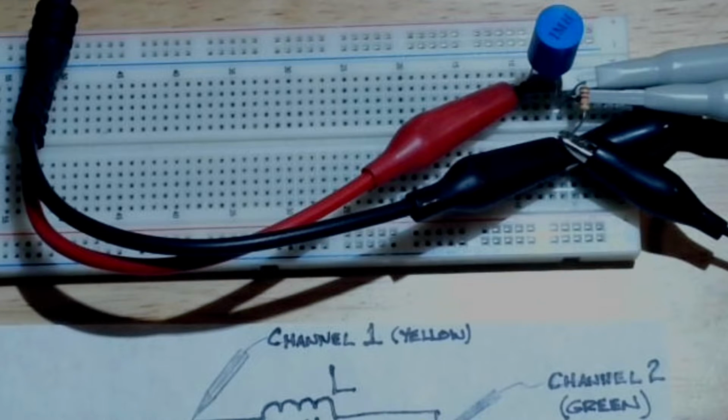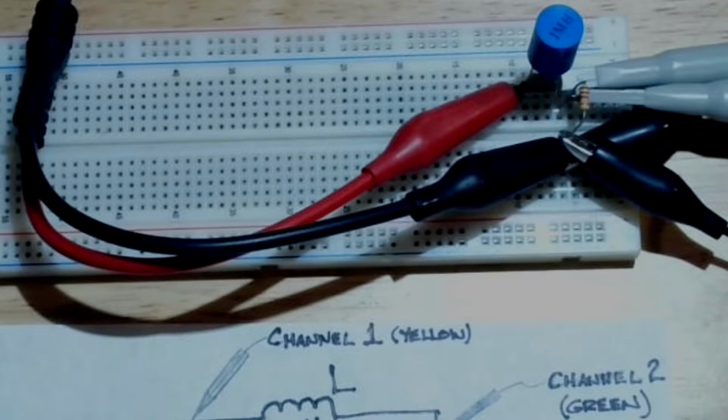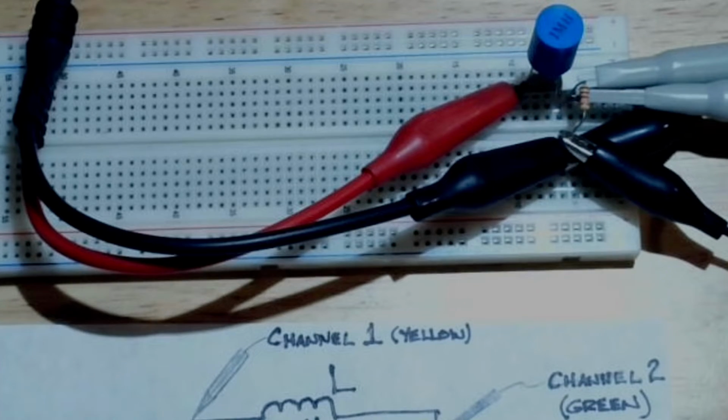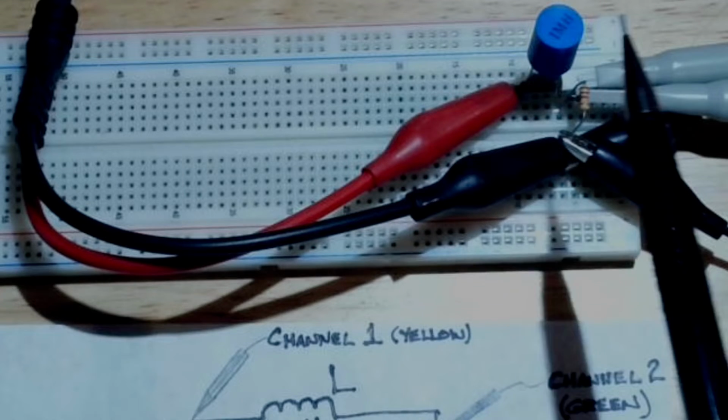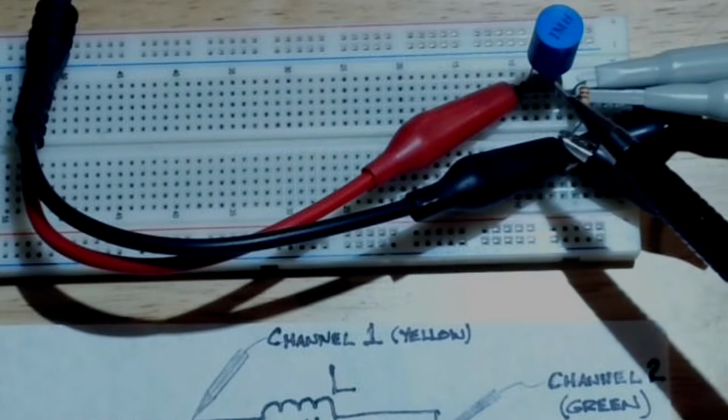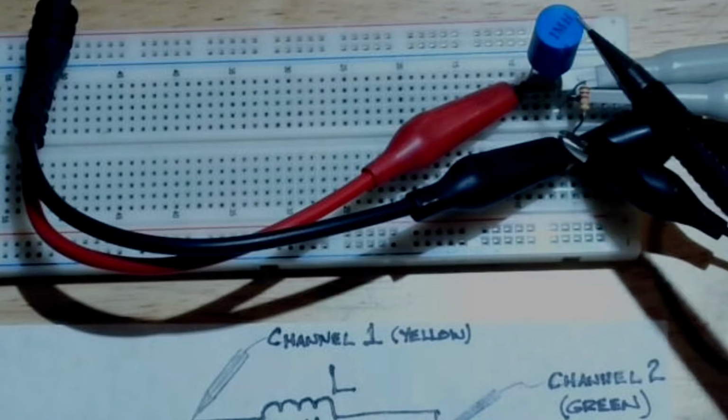Okay, ELE 155. We're still talking about magnetic induction, or inductance, which is the name of the electrical quantity we assign to things that manifest this effect. And so I have a circuit here, and I'm zoomed in on it right now, but you will see in this circuit there is an inductor. It says 1 capital mH. That should be 1 lowercase mH, 1 millihenry.